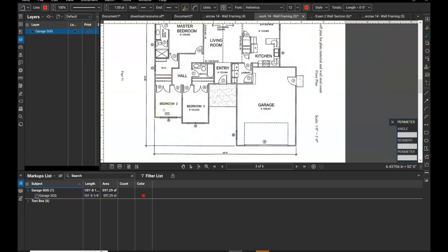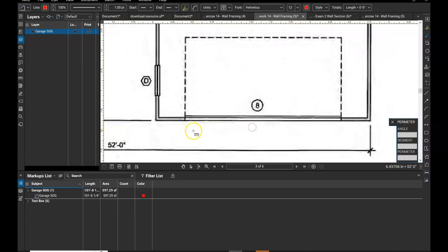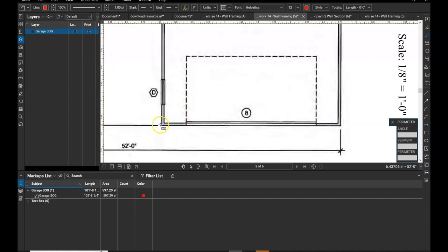Okay, and we're just going to start on one wall together. And so really on all of our different windows and doors, you're just going to go straight through except for our garage door. So I'm going to start really on my outside corner, and it doesn't snap. So a lot of plan sets that are built in CAD and built in Revit, you'll actually see your line will snap, but ours doesn't. It's an old school plan, so that's totally fine.